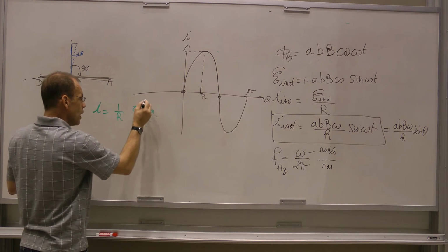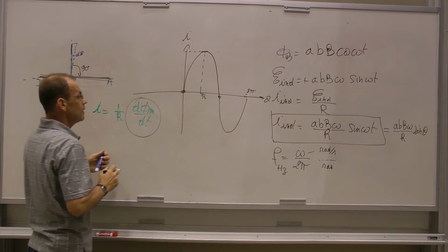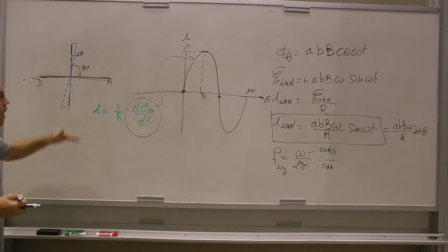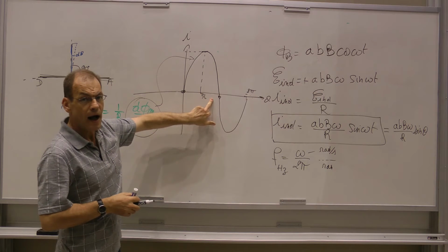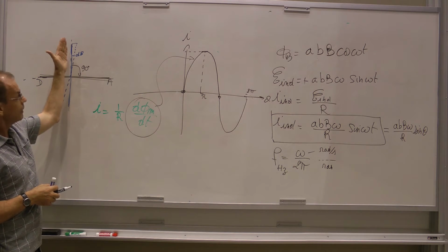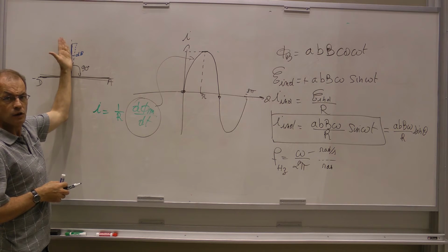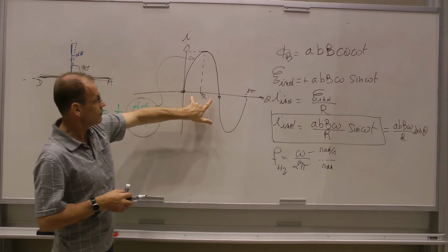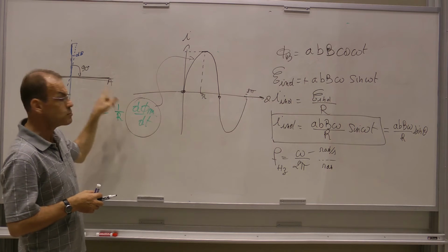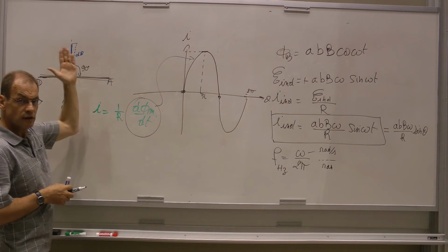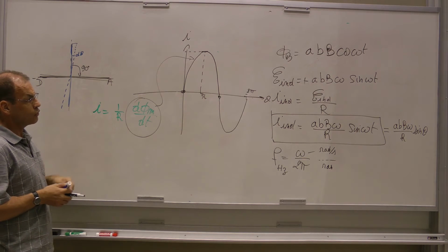And because it is dependent on d phi m over dt, this explains why the maximum happens at pi over 2 and not at 0 or at pi. Where the loop is right here, there is very little variation in the magnetic flux, which gives a current equals 0, d phi m over dt almost 0 right at that top, instantaneously 0, corresponding to a current equals 0.